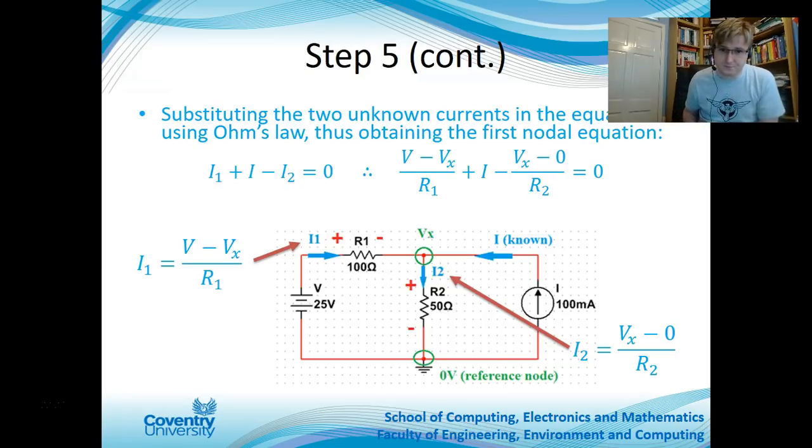As I've said here, I've drawn each of the different bits and then I just sub them all into the equation. As a quick recap, here is the positive end, here's the negative end, because this point is at the high potential, so that's connected to that. This is at 0 volts, so that's 0. Then you've got a plus there, and here's our unknown point Vx. We know that V is on this side and the unknown value Vx on this side, so it's V minus Vx for the voltage drop across R1, and to find the current through it, we divide by the value of R1, so it's V minus Vx over R1.